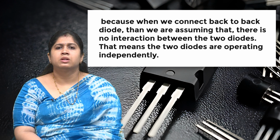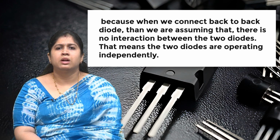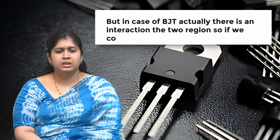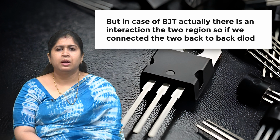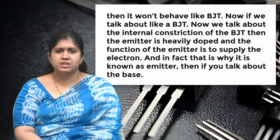When we connect back to back diodes, we are assuming that there is no interaction between the two diodes, that means the two diodes operate independently. But in the case of a BJT there is an interaction between the two regions. So if we connect two back to back diodes, it won't behave like a BJT.